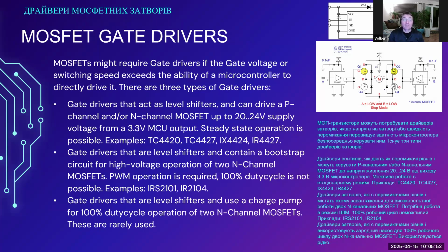If you need to output 12 volts, powered from a battery at 14.4 volts that slowly discharges towards 12 volts, an N-channel based voltage regulator can't do that. A P-channel MOSFET based voltage regulator can. It will simply turn into a low drop linear regulator when it approaches the 12 volt output voltage.